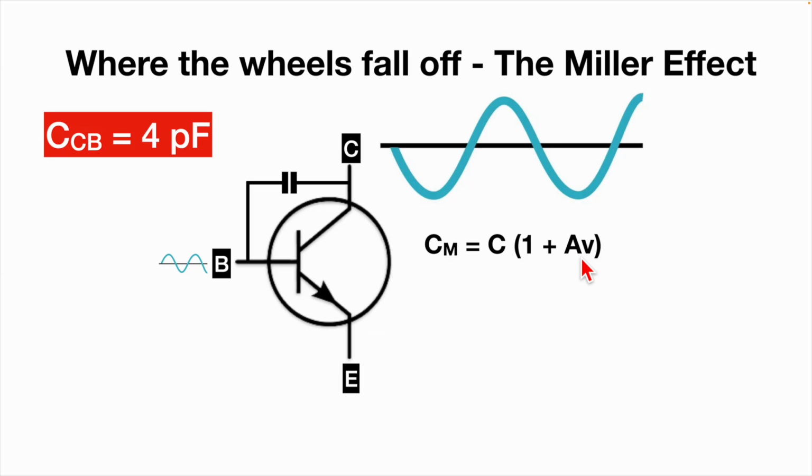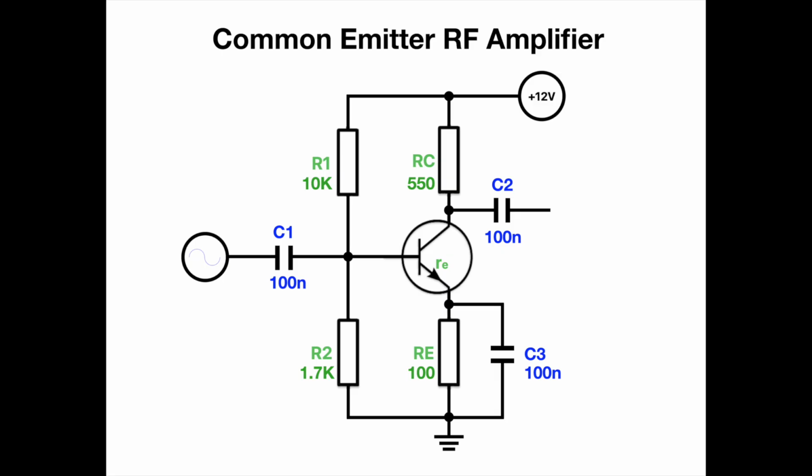So in my circumstance, if you can think back to my little original circuit, I actually have got an emitter resistor, but it is fully bypassed by a capacitor. So the only resistance which the emitter is seeing really is what we call R sub E. That's the intrinsic resistance at the base emitter junction, which is very low. It's based on the thermal voltage. It's a very low amount. In my case, it's 2.5 ohms.